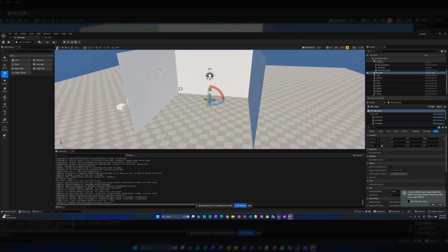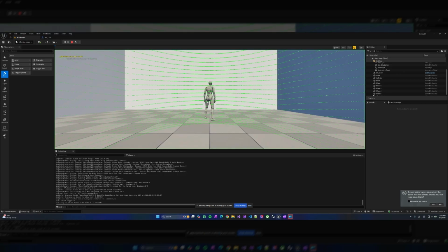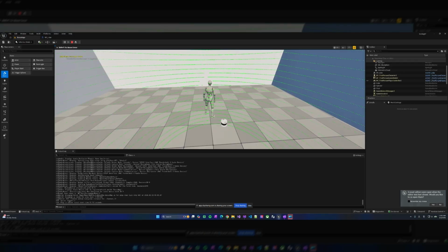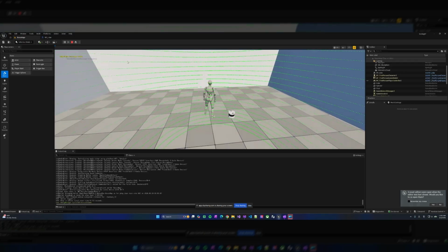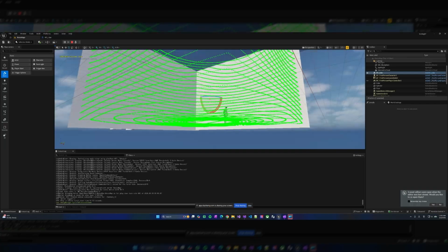So let me change the configuration. Over here, let's change the channels to 32, and let's change the field of view from -45 to +45. Compile this, save it, go over here, run it. All right, as you can see, the points now cover a lot more.